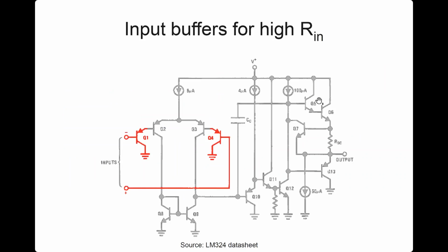So one of the things with bipolar transistors is the input current is not zero. The input resistance is not zero. So if you make a differential pair with bipolar transistors, what will be the input impedance, input resistance? 2 times R pi. Okay. So a common source amplifier will have a resistance R pi. It will have 2 times R pi, which can be quite small.